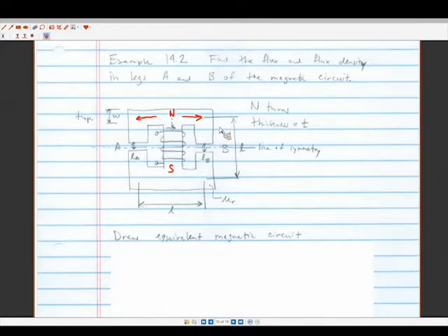The ferrous structure is going to guide these magnetic flux lines, and it's going to get to a point where there is no other place to go, but it's going to then jump through the air. Right? So anytime you see this, where you have a very small gap in comparison to all the other gaps, the magnetic flux is going to go through that path of least reluctance. As drawn here, this is a fairly small gap here and here. So the flux is going to go through this, through here, and then back up.